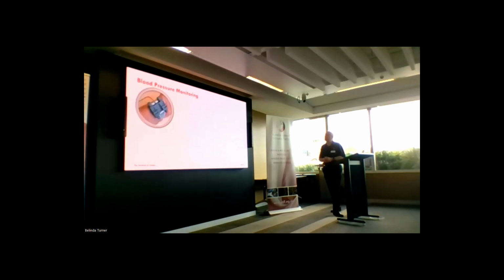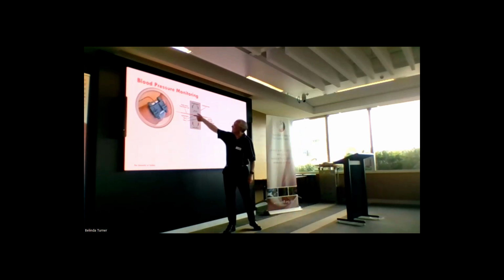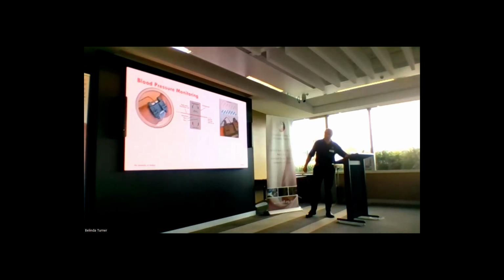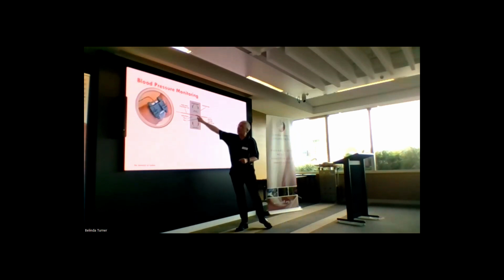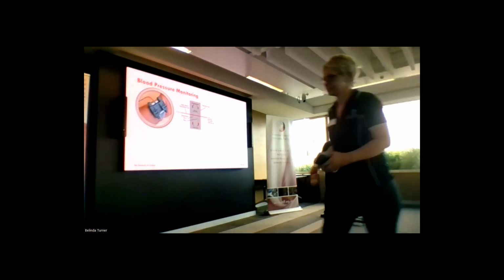But we looked around for something which was a bit more significant in terms of a problem, and decided we'd try to make a blood pressure monitoring wearable. And the approach to this was to use 2 of these fibres placed across, if this is the radial artery on the wrist, 2 of these, and without the equations here, but basically, if you can get the timing there, then you can get the velocity of the pulse going through the artery, and with a 2-point calibration, you can then get to the blood pressure.